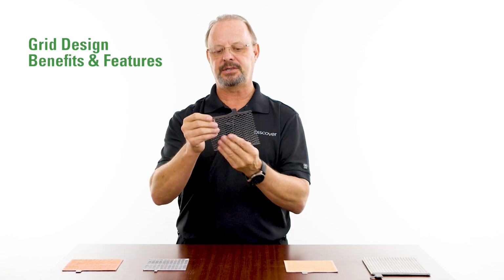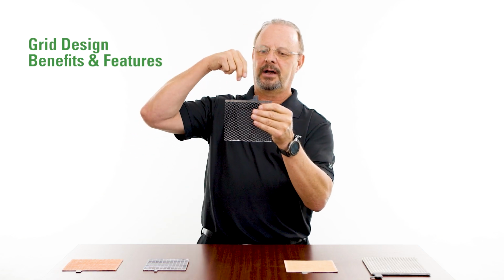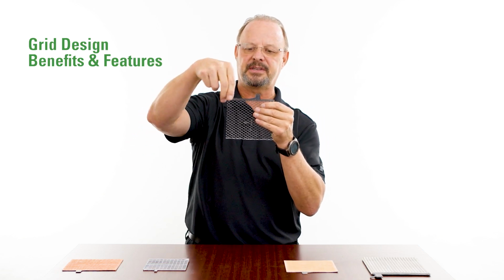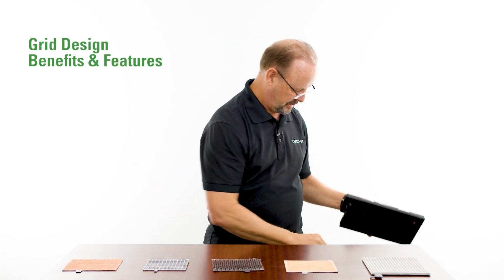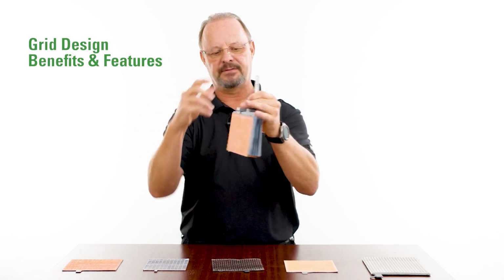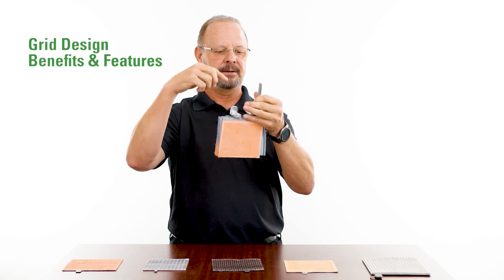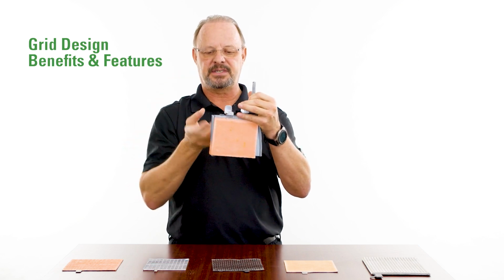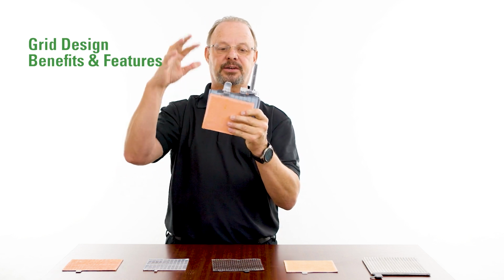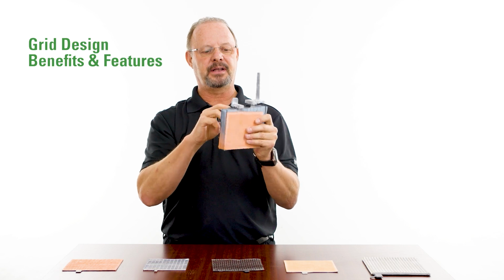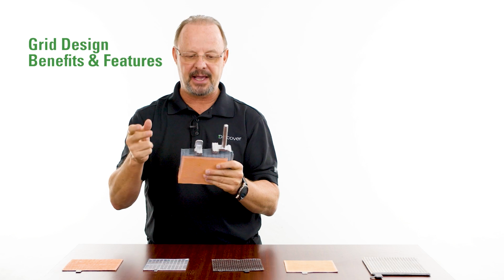When you're producing batteries using expanded metal grids like this, in the production process, you'll put hot epoxy across the top of the cell that helps to hold that plate down. So in an expanded metal element made up of a number of plates, you'll see epoxy placed along the cell here and on the other side, and that helps to resist the growth of an expanded metal grid upwards. And you don't want it to grow upwards, because if it grows upward, the positive plate can short out on the negative cast-on strap later.